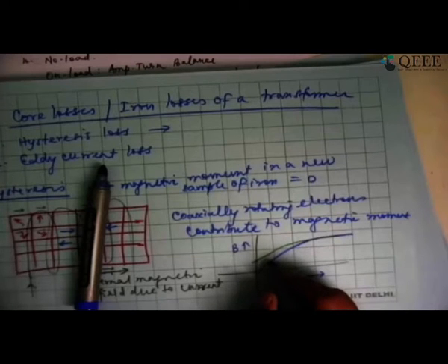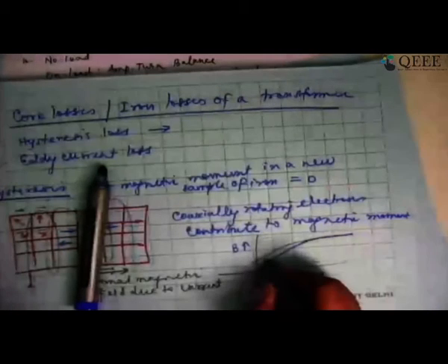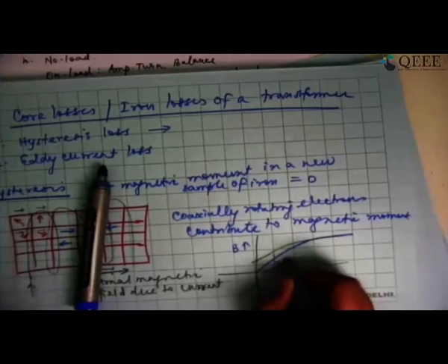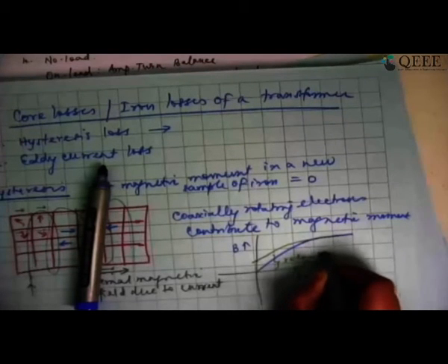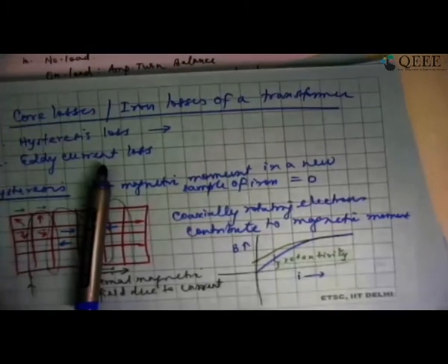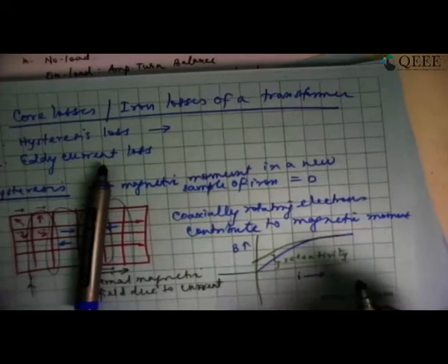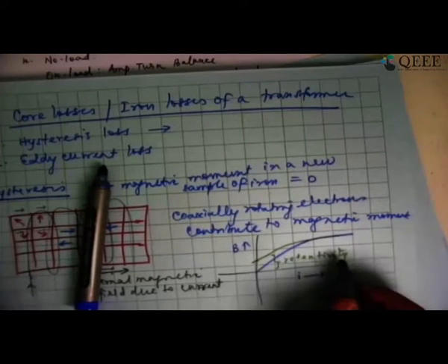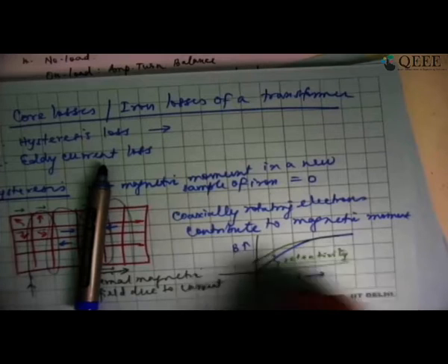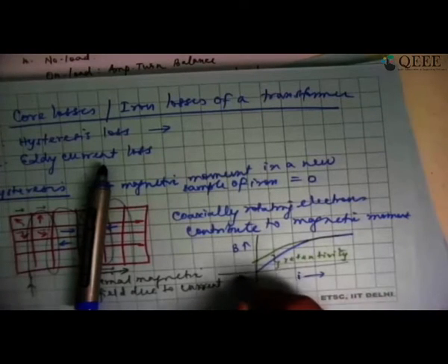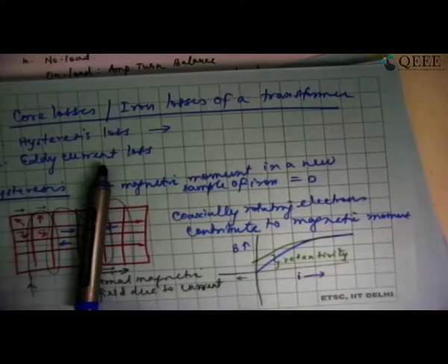It retains some amount of magnetic field. So this is known as retentivity. It is essentially the retaining or remnant flux density. You can say remanence. So some amount of flux is remaining, because of which I call that remnant flux density or retentivity. Now I start increasing the current in the opposite direction.